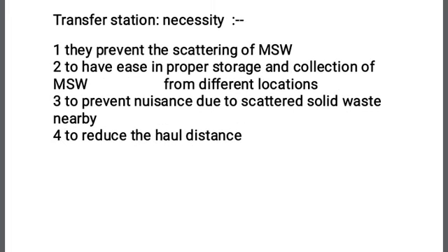Next point, necessity of transfer station. Why is a transfer station required? Why is there a necessity of a transfer station in the city or town? Because a transfer station helps in preventing scattering of municipal solid waste due to stray animals or wind blow.